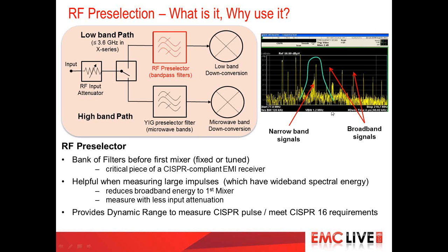The log amp gives our display in terms of dBs, or decibels. Now, when spectrum analyzers were first invented, they had an analog IF, in that all the components were analog or mostly analog. And by going to digital, really the key improvement was improving amplitude accuracy. With digital, there are no longer any switching uncertainties or amplitude uncertainties related to the display, so there's a significant improvement there.